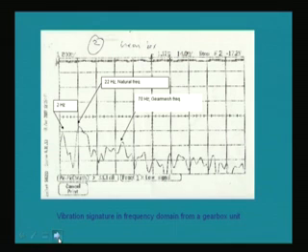Another signal: you can see in this particular one, these peaks are more predominant, they are higher in amplitude, and this is the actual signal taken from a stone crusher unit. Just one week before the failure, which I showed in the previous slides, when a crack developed in a particular crusher unit, these are the indicators which we measured one week before the failure.